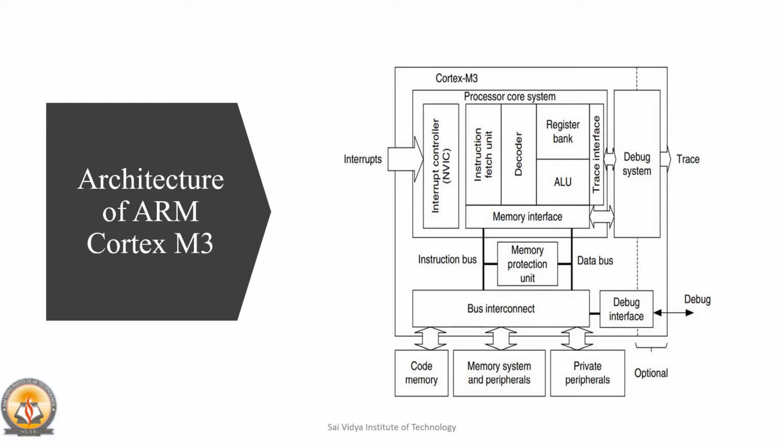Now the memory protection unit, also called the MPU, is an optional component of the Cortex-M3 processor that can improve the reliability of an embedded system by protecting critical data used by the operating system from user applications. How is it done? By separating processing tasks, by disallowing access to each other's data, disabling access to memory regions, allowing memory regions to be defined as read-only, and detecting unexpected memory access that could potentially break the system.